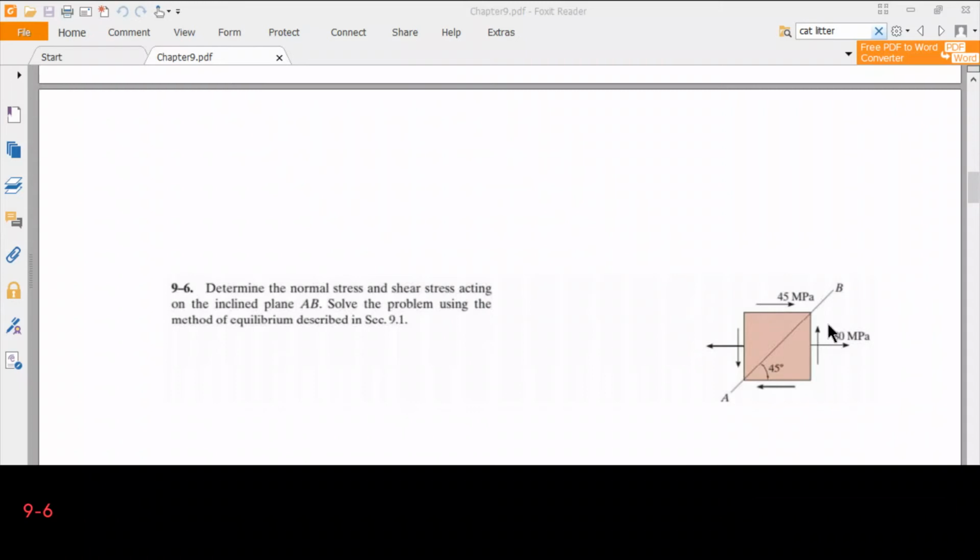Now we have the shear stress. It is positive. We have sigma x. If the horizontal axis is x, we can say that it is 80 megapascals, and we have a shear stress also positive, which is 40 megapascals. So the vertical component, the normal stress, is 0.